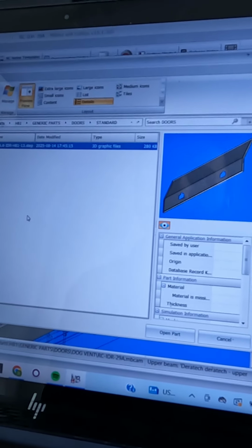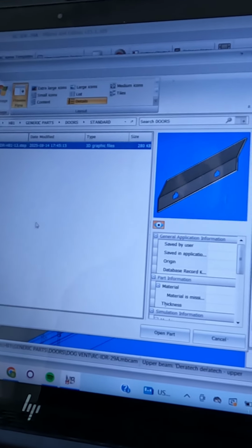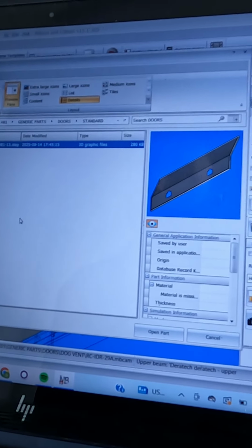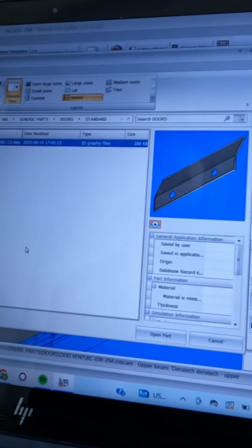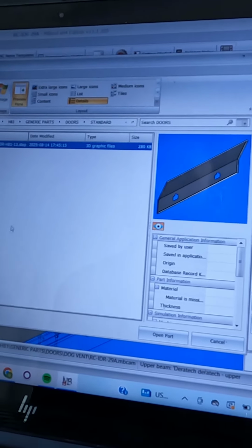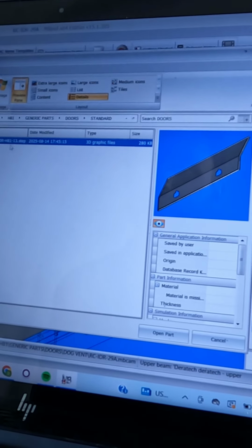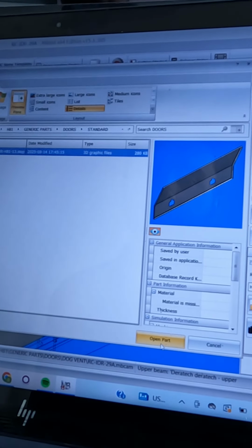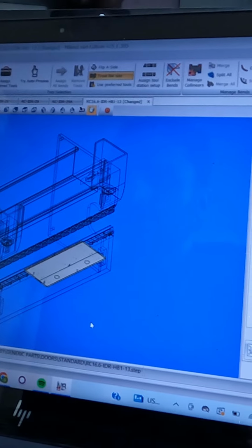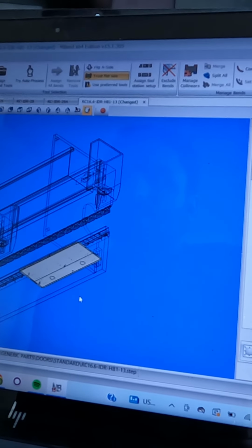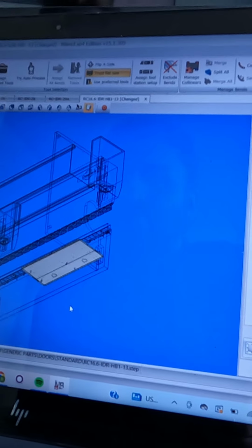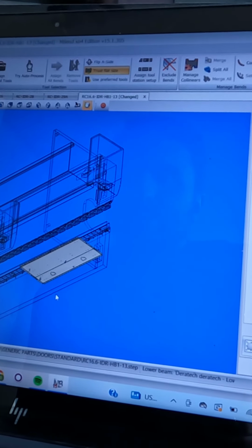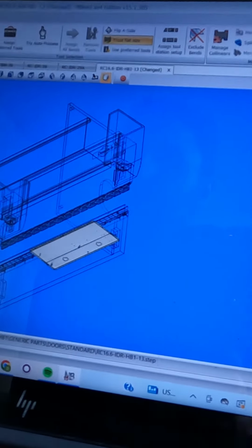This is the process we go through for every individual part of a canopy or tray build. So for this particular part, we have a canopy door. Each part is exported from our CAD software into a library where we can then select the parts required. It then comes into a software that we call offline processing, and this software is what we use to generate the G code required to tell the CNC press where and what to bend and the angle to bend.